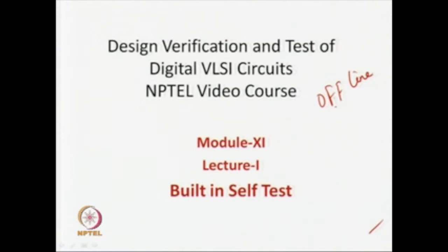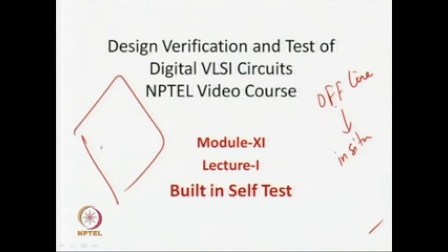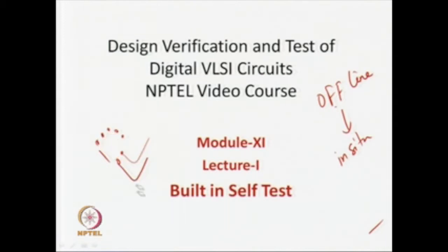The next level of testing after offline, and all lectures till now are offline, is something called in situ testing. In in situ testing, your chip is already placed in the board and you want to know whether it is still operating fine, because that is the only way you can debug your circuit if there is some problem in the system. But it is very difficult, as the chip is already fabricated and soldered onto your motherboard. It is very difficult to apply test patterns, because it is hard to get access individually to the chip, as it is connected to other parts of the circuit. That actually makes your life very difficult.